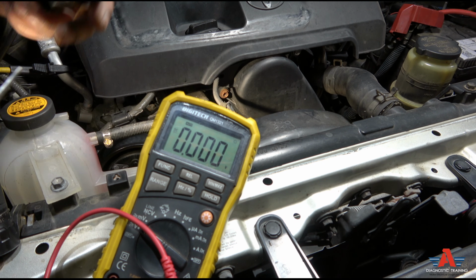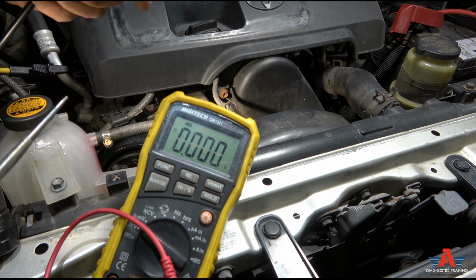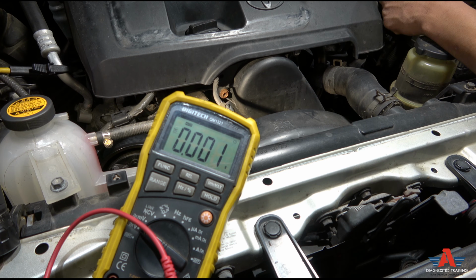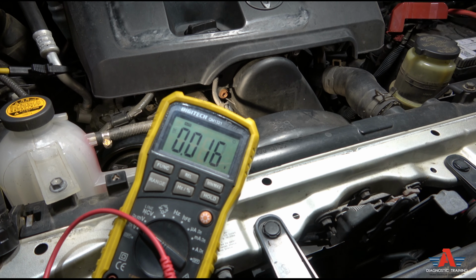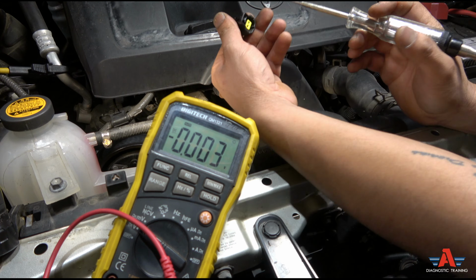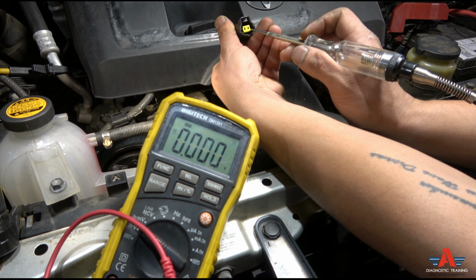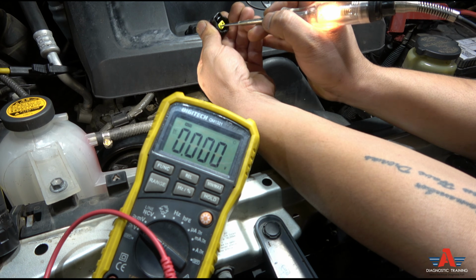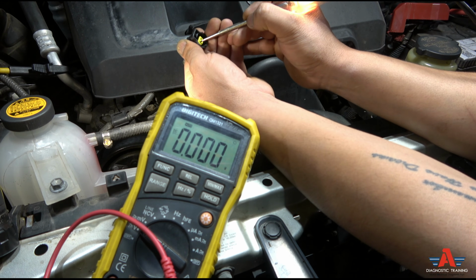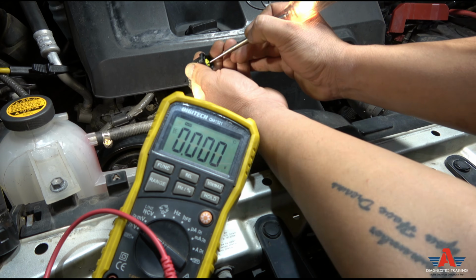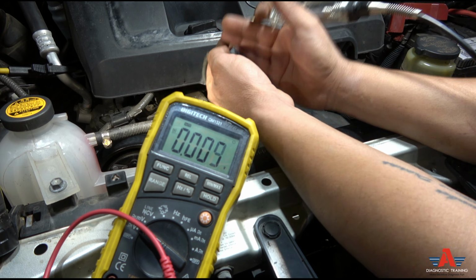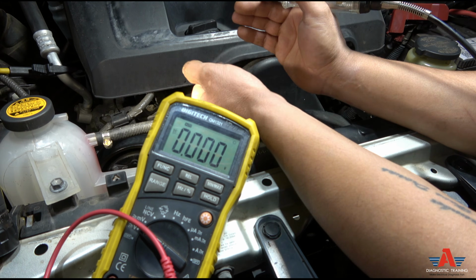All right, so I'm going to go to the battery positive this time because we're looking for earth. I'm going to go on this pin because we already verified that red wire is my 5 volt. Now touch that pin. My test light lights up. Hope you guys can see that. My test light lights up. I got the earth here. I got 5 volt and I got earth coming in here.